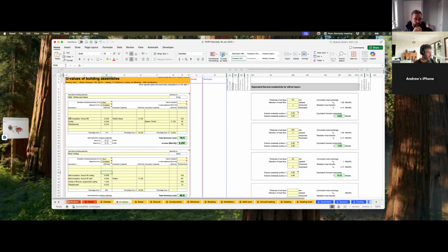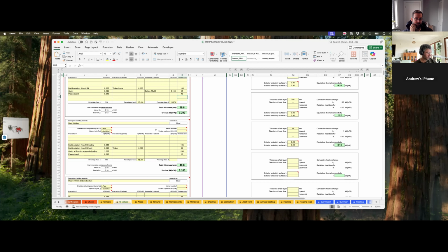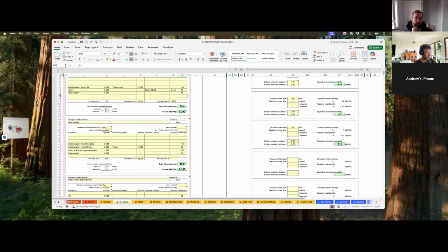So yeah, there's your wall build up. So you've got your R4 in the timber frame, your 45 mil cavity, which is your service cavity, and then your 13 mil plasterboard. It's 45 mils to allow for a lagged hot water pipe. And it also gives you plenty of depth for your power points and your light switches and everything.